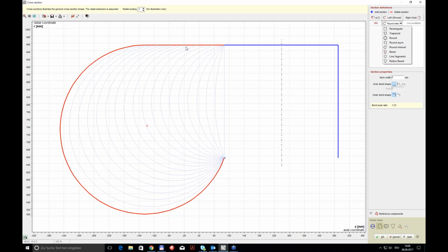Okay, and perhaps the last question on CFturbo is, I notice you changed the meridional contour in CFturbo from the default. Is this to improve the efficiency of the impeller or meet space requirements? Are you looking for a constant velocity across the contour?